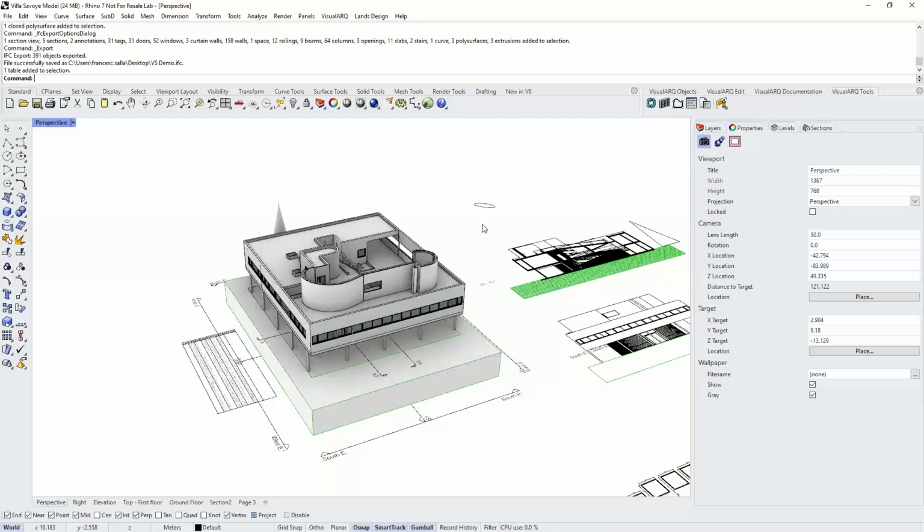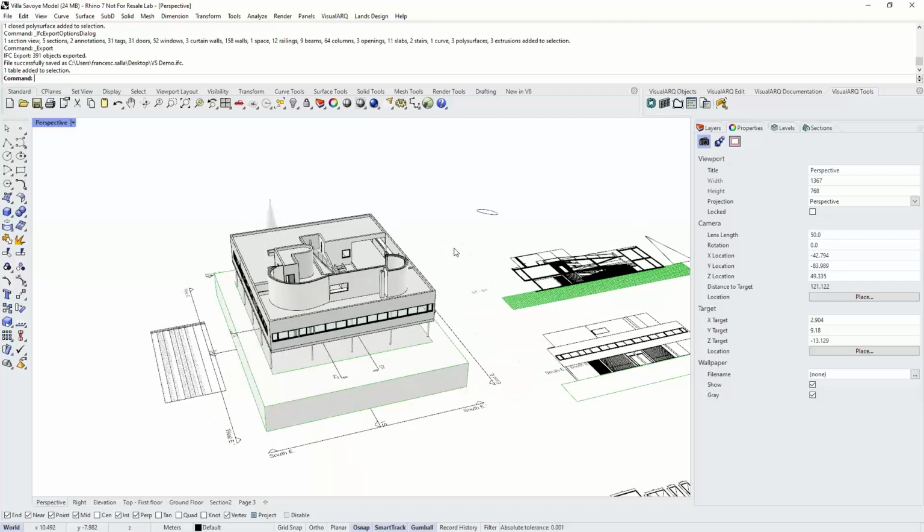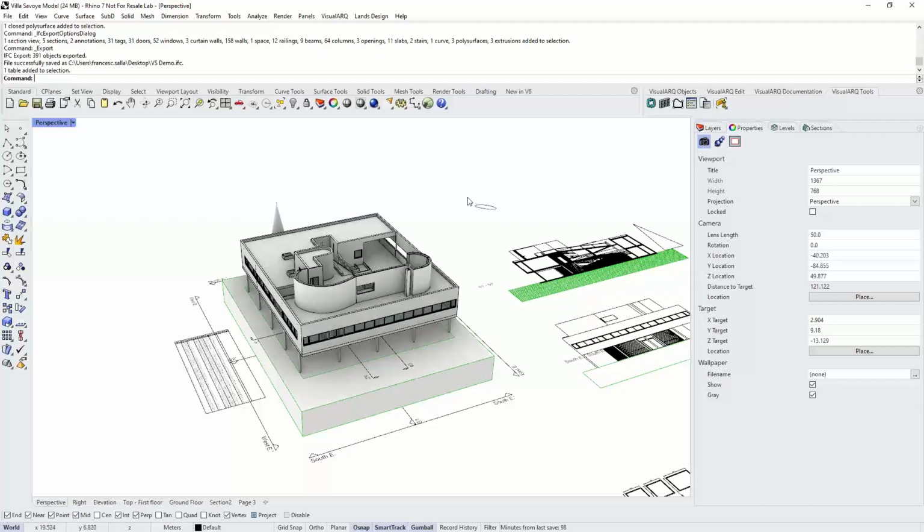But what you can do is manage files through external references. So you can have a master file and import the files that other people are working with as inserted files, but they need to be embedded and linked. Otherwise, they won't be displayed properly. And then they work as blocks. When somebody has changed their file, you just need to go into the block manager in the master file and update those blocks to see the changes.